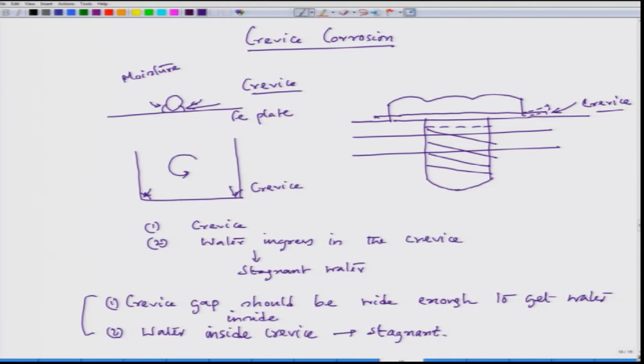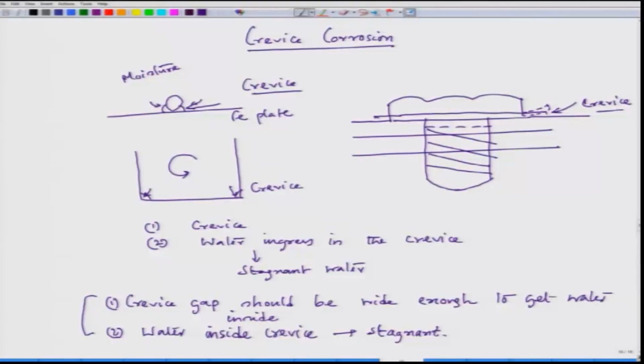The rate at which the dissolution takes place in that region would be so high that the surrounding region might look very clean, but in that region there could be corrosion in the depth direction. That means a small gap forms, and that corrosion point can progress in the depth direction. So, if this is the thickness of that wall, at times this wall can be punctured and there could be leakage, and this is the level of crevice corrosion that is possible. Here also there could be crevice corrosion around this region. The corrosion would be so fast that even without giving any signature, it might leak the container.